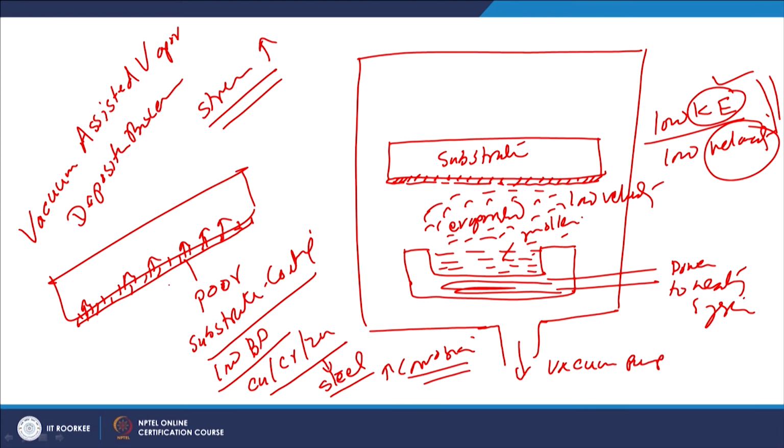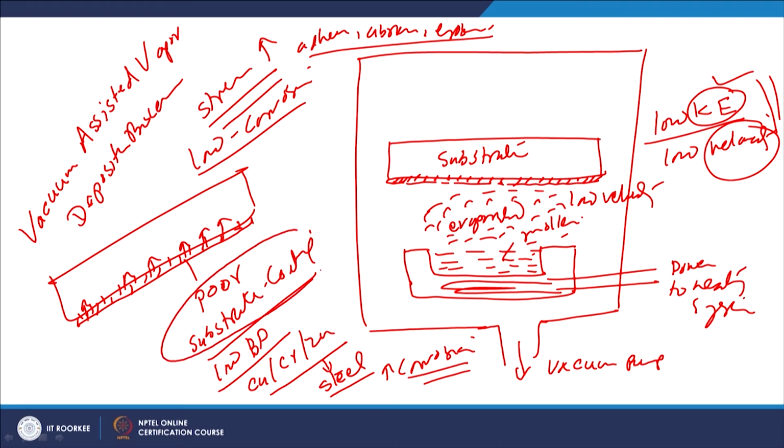So this kind of chemical composition modification of the surfaces is good, especially when the stresses acting on the functional surfaces are very low, like in corrosion conditions. But if the stress magnitude is high, like under adhesion, abrasion and erosion, then this kind of coating will not survive and will get removed from the functional surfaces easily, and this is primarily attributed to the poor bonding of the coating material with the substrate.